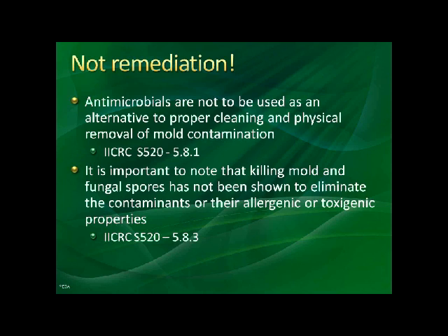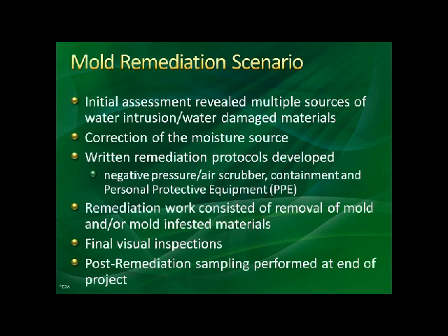A good remediation scenario is: do the initial assessment, correct the moisture source, have a protocol developed, remediation done where the mold is removed, a final visual inspection by you, and post-remediation sampling and verification at the end of the job. A to Z. In a court of law, that stands significantly.